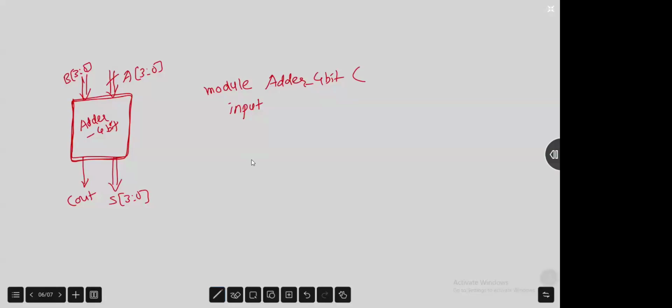अब इसमें भी आपका जो A है, तो ये कितना है? A is my 4-bit, not single bit. When we write input A, B, it understands it's a single bit. अगर मैंने सिर्फ इनपुट को A, B लिखा, तो वो हो गया सिर्फ हमारा सिंगल बिट. आर यू गेटिंग दिस? समझ में आया क्या? Yes कावेरी, that is of your A 3 down to 0, B 3 down to 0. लेकिन यहाँ पे हमारे जो इनपुट्स हैं वो कितनी बिट हैं? 4 बिट हैं. So that is known as vector and it is known as your bus.